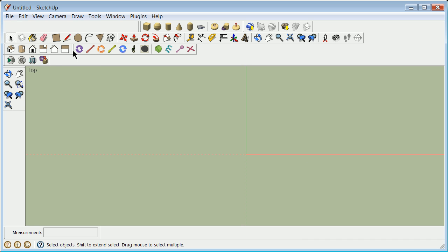All right, so I can either click here, or in this program I can type L. I click there, I get in the general direction, I use a less than, greater than, so I'm going to go 300 feet. I'm not sure of my units right now. 300 feet, comma, 0 feet, comma, 0 feet. Once again, be aware that you need that third coordinate in many programs. And if you notice, I took that 300 in the X.